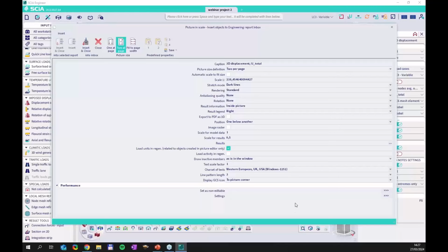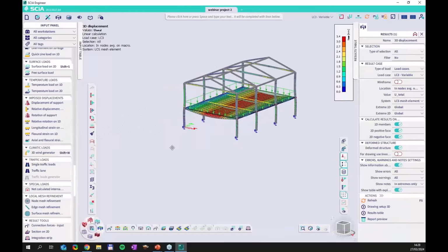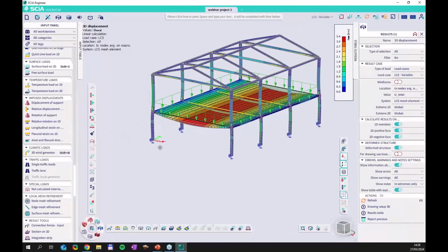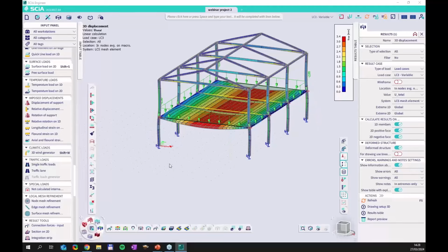Good. Now, one thing I didn't show yet, let's first add this into the inbox. One thing I didn't show you yet is another way of modeling something, which is through the marking menu. That is for, let's say, maybe more advanced users, or it depends on how you like to model. But this is sort of an invisible helper. You have to know that you can open it by holding Alt and right mouse button. And then you see that if I hold these keys, the marking menu appears.